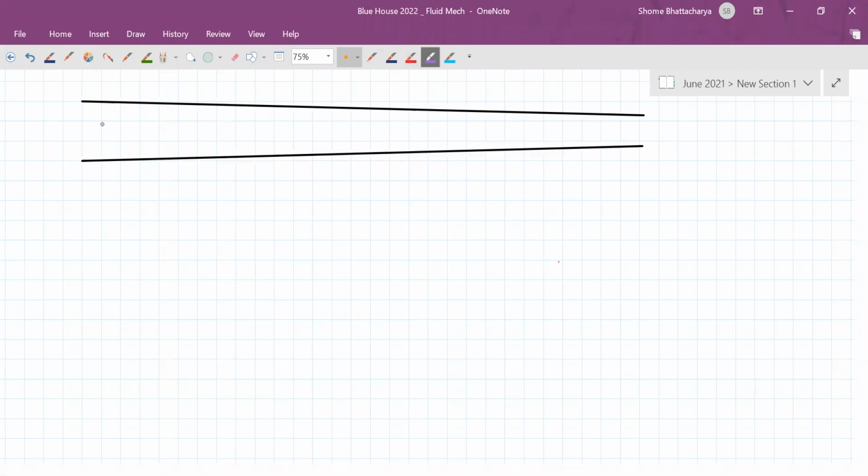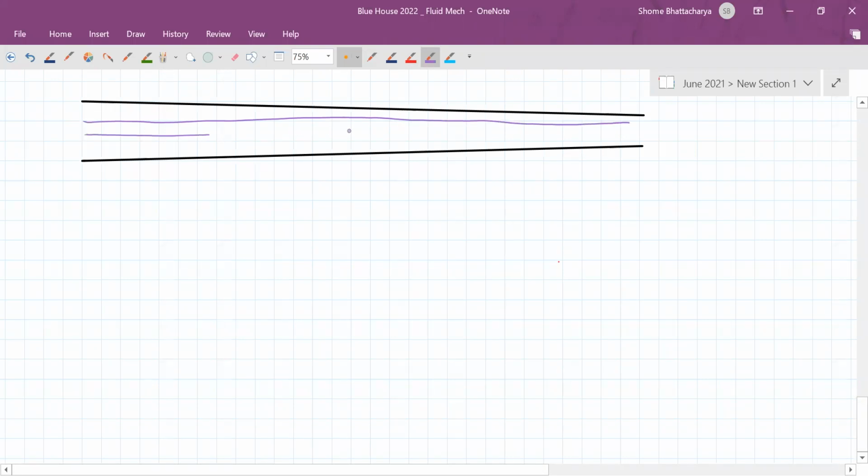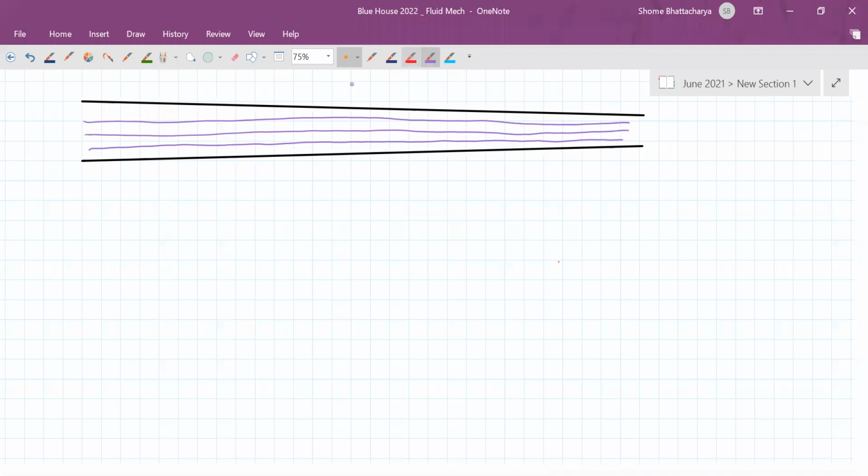So in this kind of situation, if there is a fluid flowing in streamline motion, and we draw the streamlines quite accurately, then we'll already be able to understand that, no matter whether the direction of velocity is left to right or right to left, the density of packing of the streamlines is lesser in the section where the area is more. So let's say this area is A1, and in comparison this area A2 is quite a bit less.